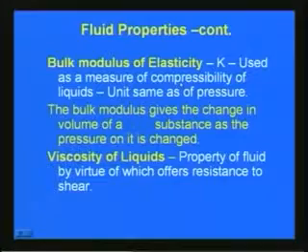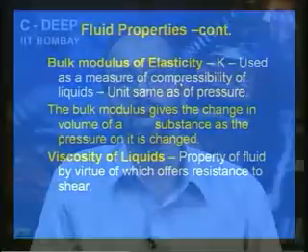So, especially when we are dealing with gases, the compressibility is very important, and also for compressible fluids and compressible liquids, this bulk modulus is very important. The bulk modulus gives the change in volume of a substance as the pressure on it is changed. Generally this is expressed with respect to solids and also with respect to liquids.